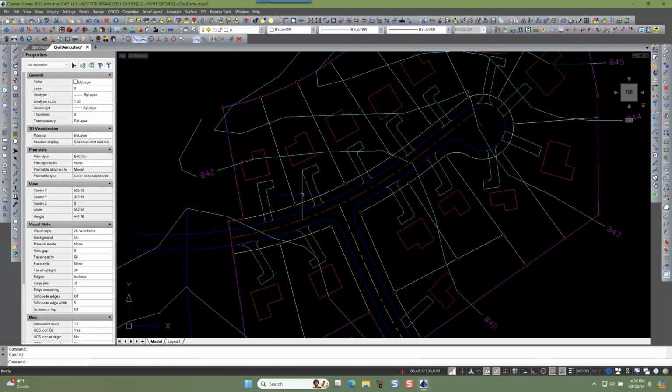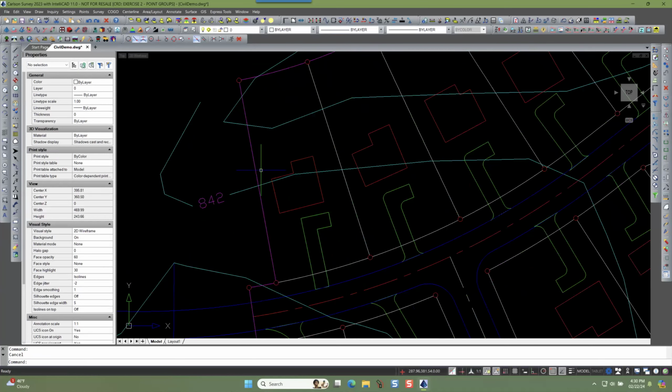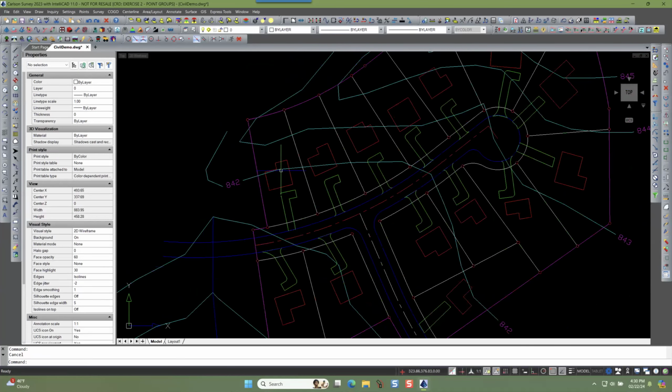You know what? It's not working over here. That might be an AutoCAD only type of thing. Anyway, it lets you pick. It's sort of like matching. You can tell it, I want to put this on the same level or same layer as this. Oh, wait a minute. Let me see. That might have explained it. It says set level. So it is working, but it would only work on MicroStation files that use levels instead of layers.